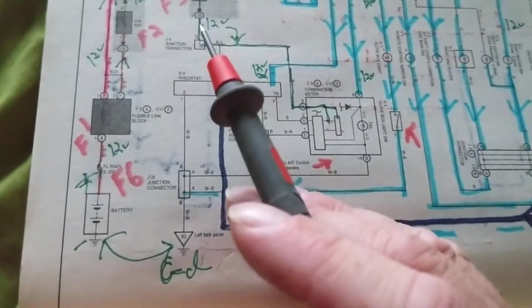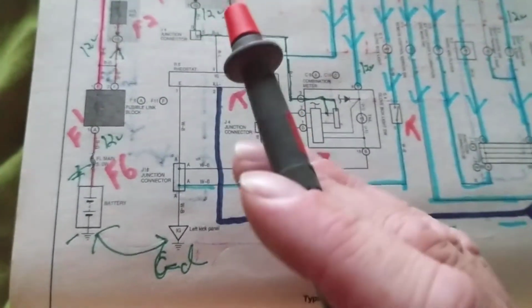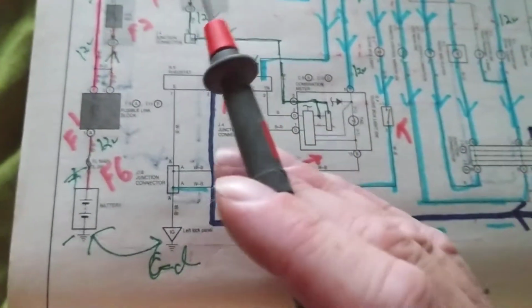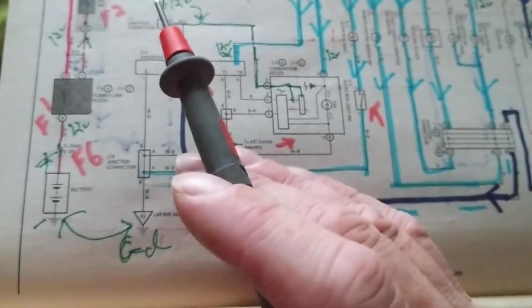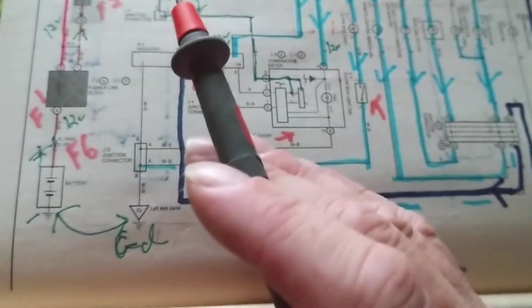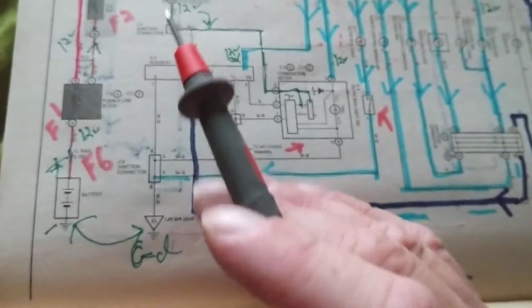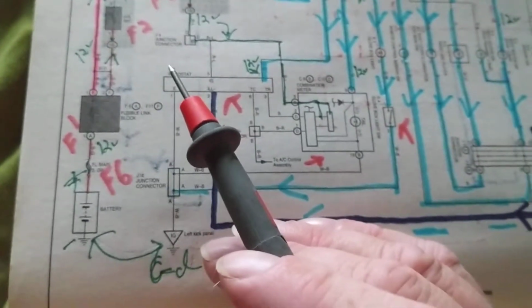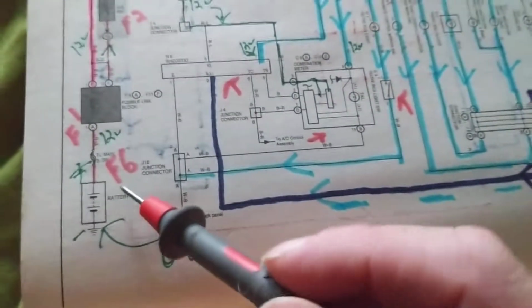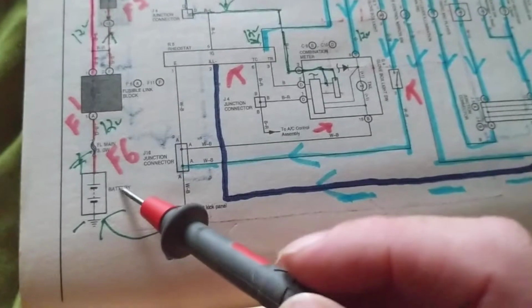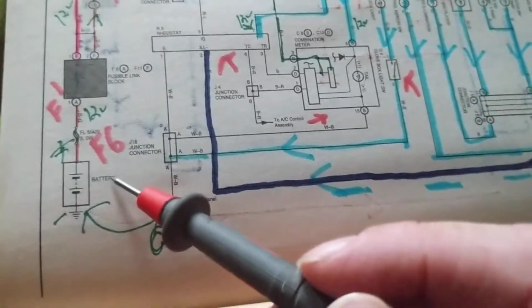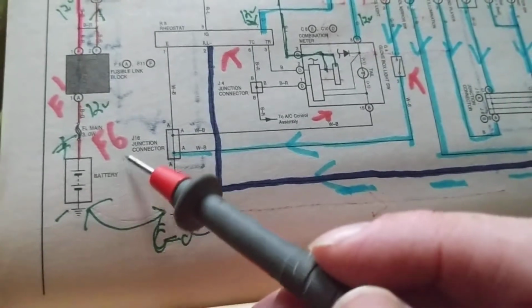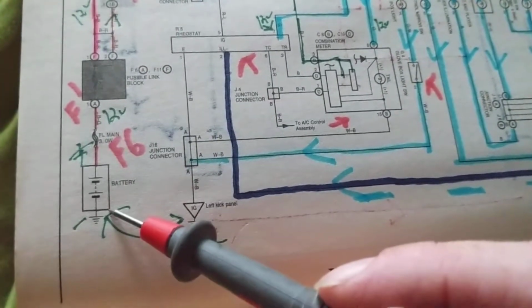Now, with temperature, obviously the battery voltage changes. The cranking amps, and you have to know cold cranking amps. Cold cranking amps is at 0. Cranking amps is at 32 degrees. You have to know those things. The battery is at 12.6, but maybe at 70 degrees, 80 degrees. But as the temperature goes down, obviously the output will drop.